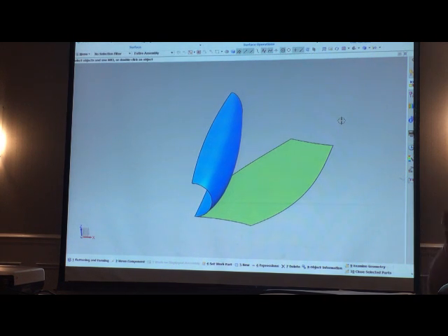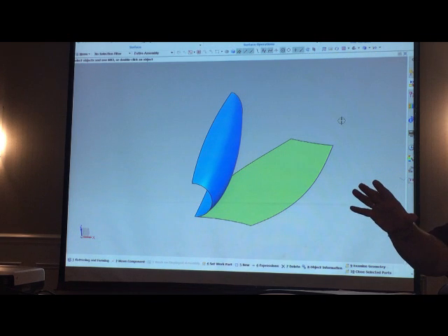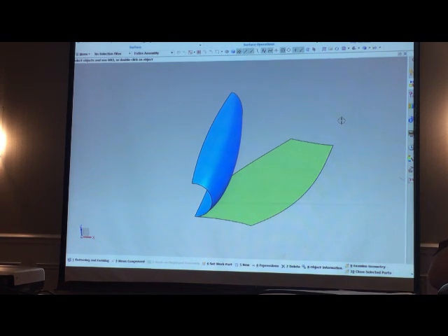Now, before anybody gets excited, there's no physics involved in this. There's no setbacks, no K-factors, no neutral axis or anything like that. This is pure math. It uses conservation of area. What it basically does is it broke that surface into like a finite element mesh. Then it mapped those little squares down onto the flat and tried to get them in such a way that they would maintain their area and perimeter. So as to as faithful as possible represent the same area but flattened out. But it works pretty damn good.